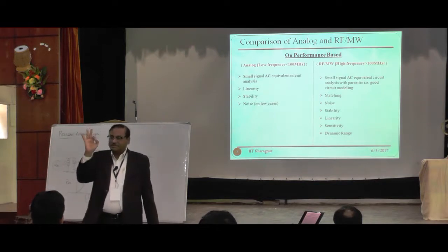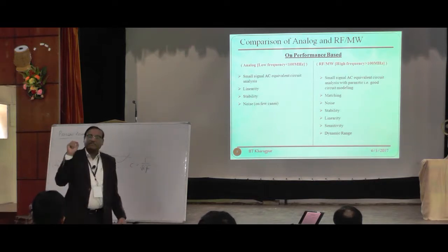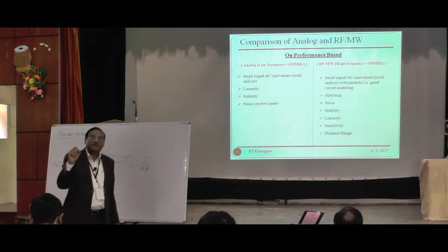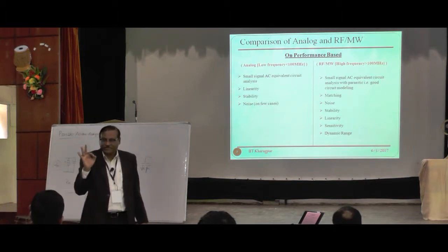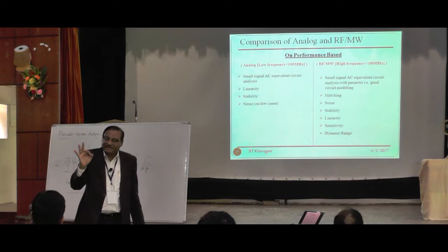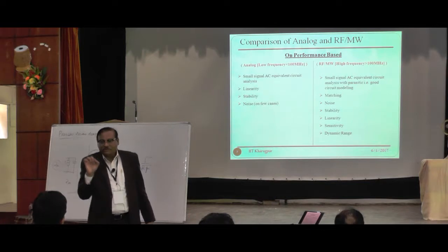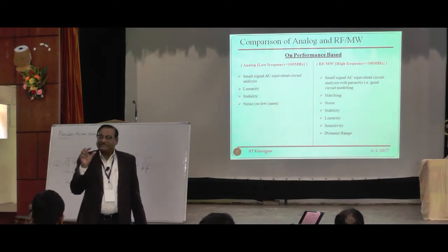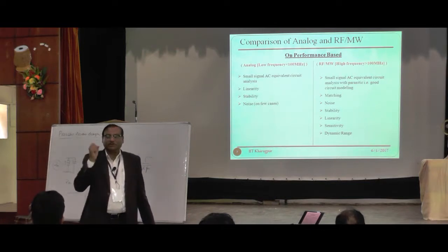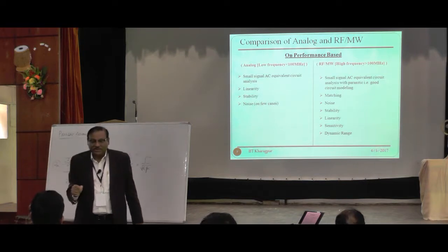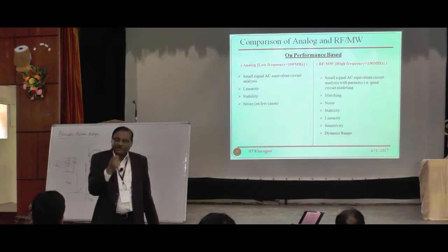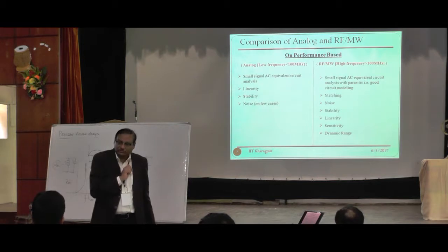What do you do actually? You introduce some kind of a biasing voltage. What do you mean by biasing voltage? It's called quiescent bias. So you actually bias it, and then your input signal is very, very small around that biasing point. So within that, what is that? Suppose I am giving 1.2 volt quiescent voltage, and I am varying the input signal in microvolts.